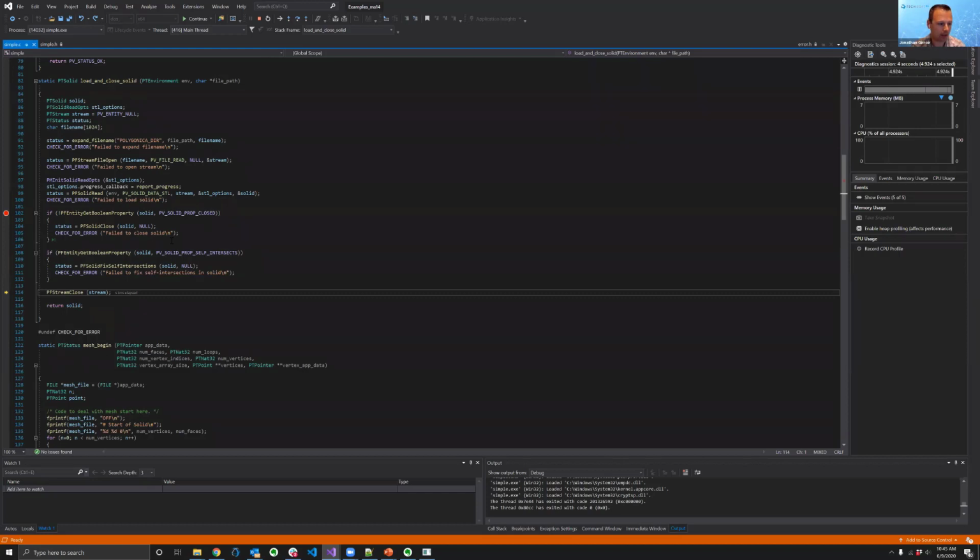The triangles or polygons might, the orientation of the edges in which they're declared may be in opposition to one another. So normally you declare a triangle like vertex 1, vertex 2, vertex 3, and they kind of go in a circle in the same direction throughout your mesh.